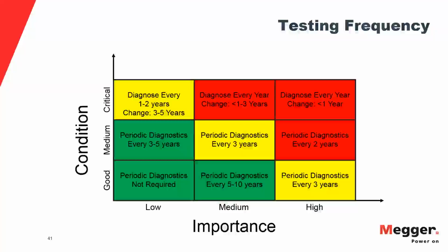Just to add to that, the IEC standard is very strict and very detailed in terms of the measurement circuit that you're using and how these signals are processed and how the signals have to be integrated. Pretty much like partial discharge, these signals can occur over a very wide frequency band that stretches from some lower kilohertz to, as Jason said, the megahertz. So for instance, 150, a few hundred kilohertz, and then up into the megahertz is this partial discharge frequency band.